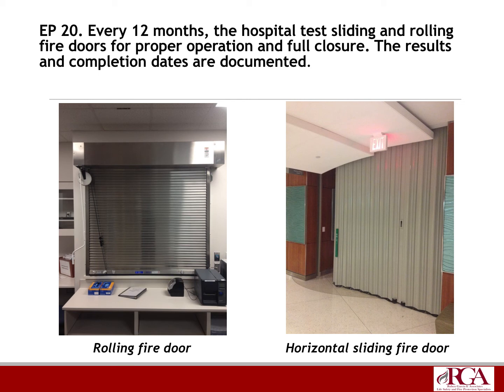Now, your fire alarm vendor will check these to make sure they drop out on fire alarm as part of their relay interface testing, but they're not checking the integrity of these doors. They're not letting you know, hey, it didn't close all the way, or hey, there's some other issues. They're not going to check the exit hardware.